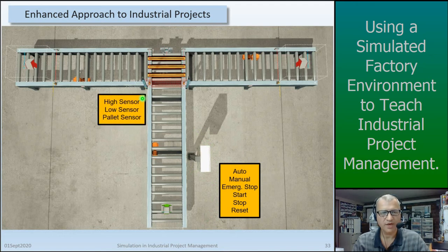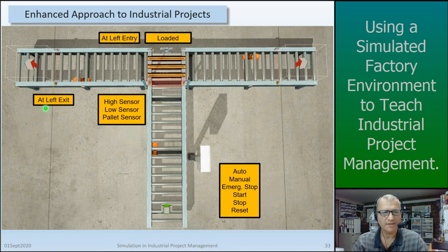For the sensors, I have a high sensor, a low sensor, and a pallet sensor. Pallet loaded capacitive sensor, at left entry a reflective sensor, and at left exit. I also have at right entry a retroreflective sensor here, and at right exit a retroreflective sensor here.